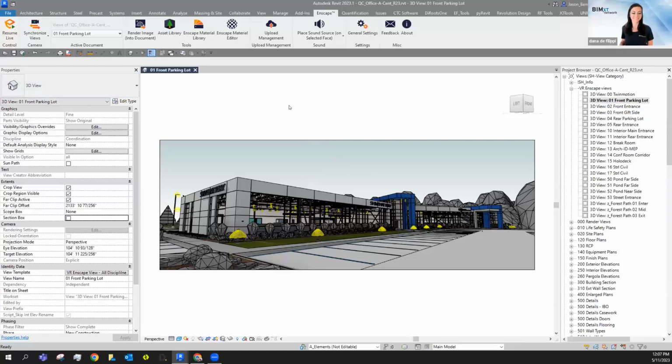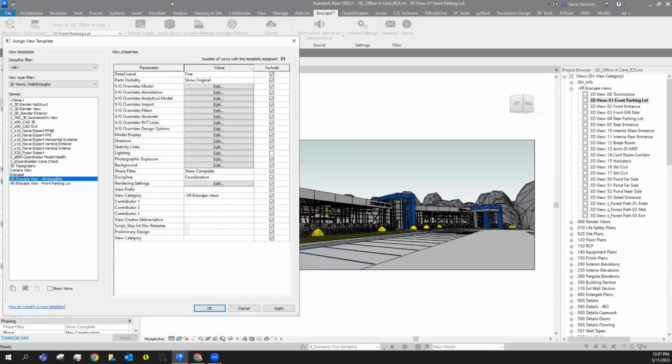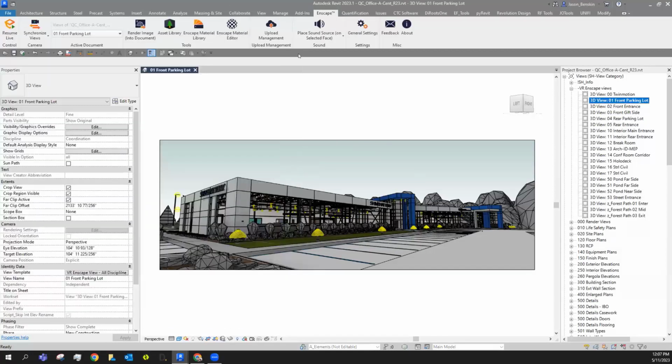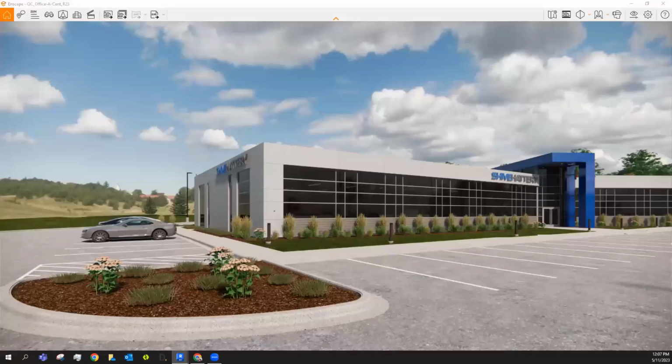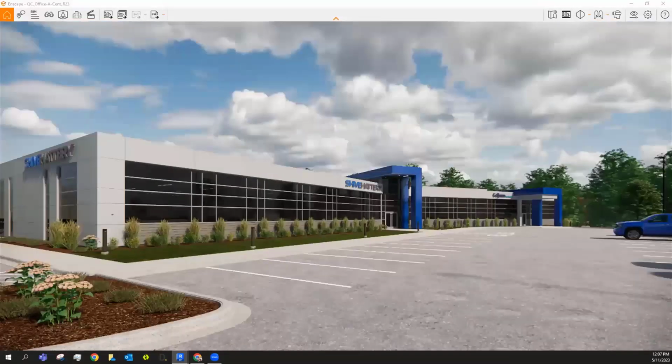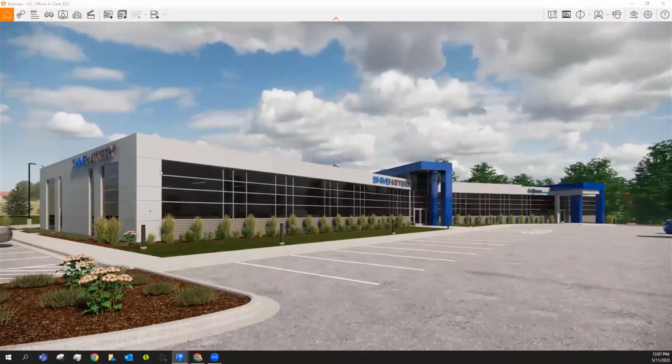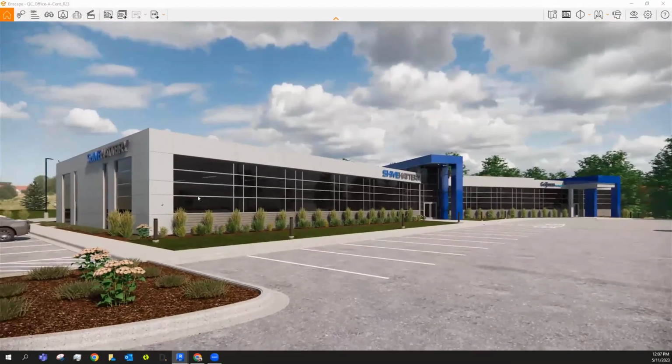So you guys can see my screen now? Sure can. Okay, great. So the tip would be to start off with the camera view. It doesn't necessarily matter the contents of the camera view right off the bat. View templates are always awesome for getting things set up and establishing everything else. And once you get that camera view set up, launch Enscape from that.